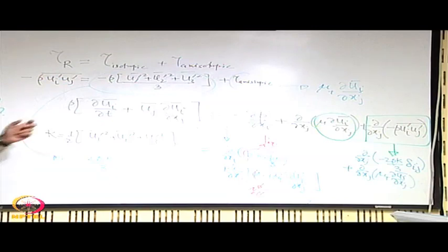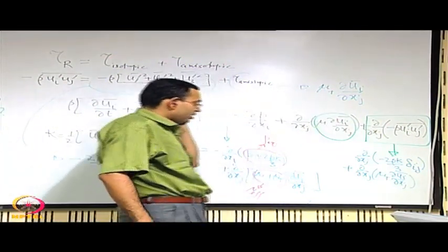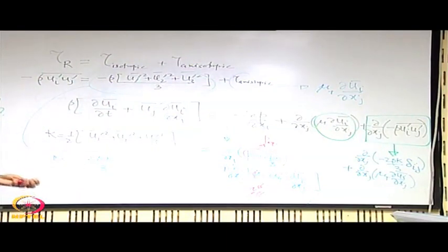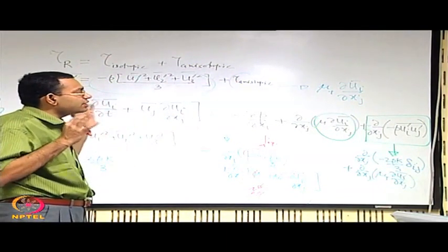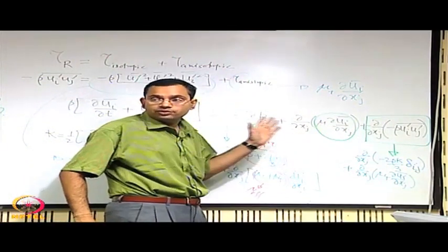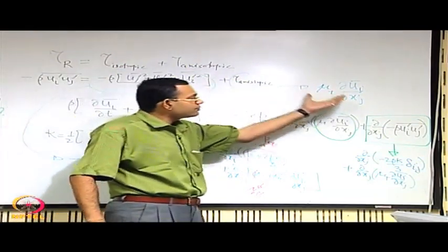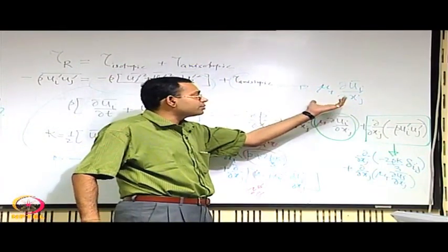And just this form was originally introduced by Boussinesq, and of course this is just like a hypothesis, it is not that this is exact, and we have discussed what the philosophy is. The philosophy is a desperate act of closing the system of equations, and then of course it might be written in this form because it is an acceptable constitutive form.